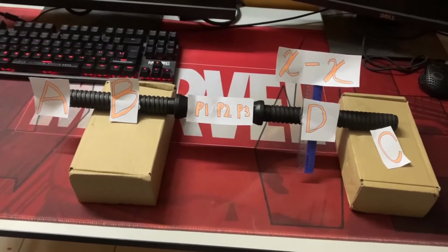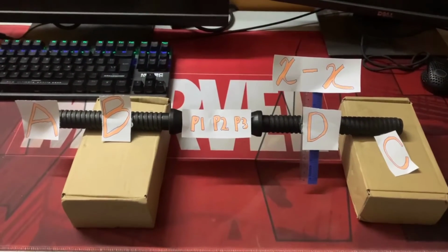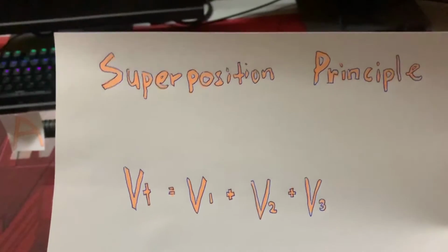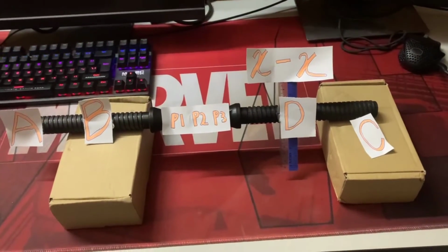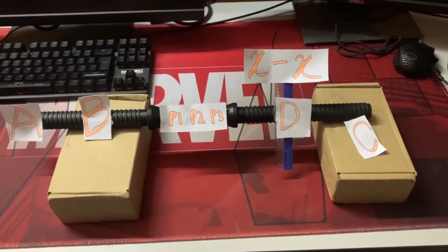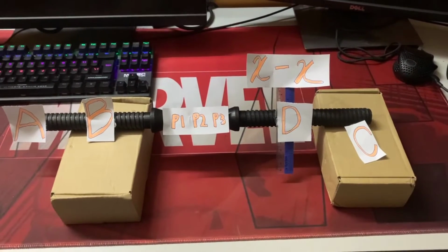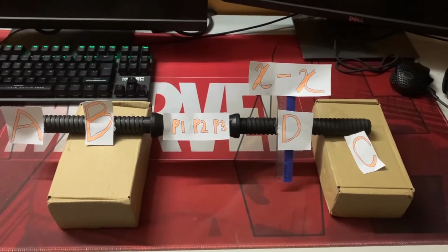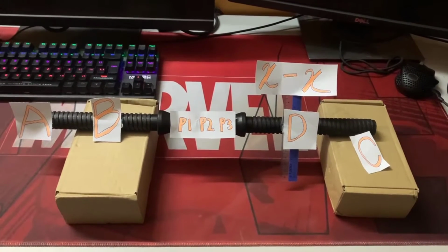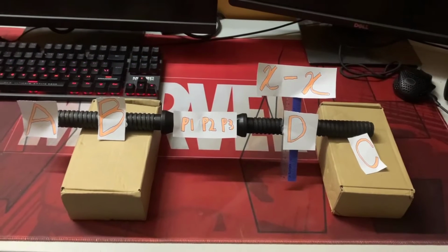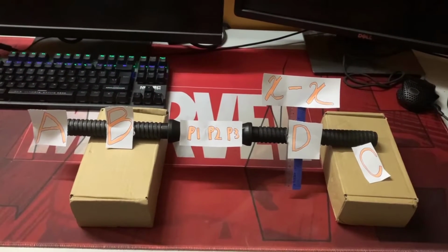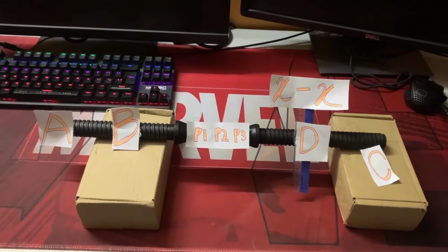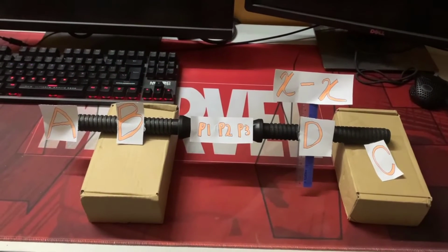Then we apply the superposition principle, which is that the total shear force is equal to the summation of shear force at section XX when independent loads are applied at P1, P2, P3. Lastly, we need to discuss whether the measured and calculated values of shear force at section XX obey the superposition principle.